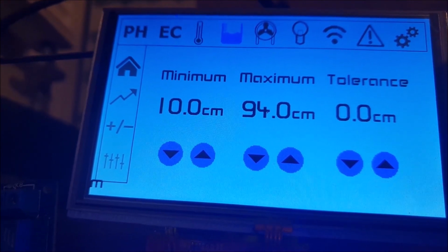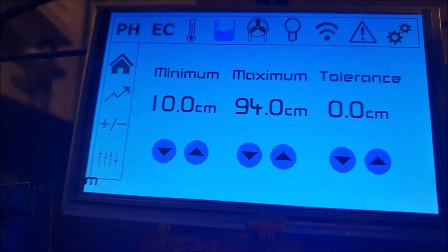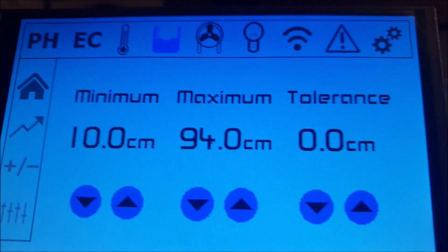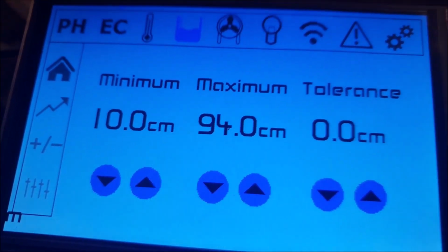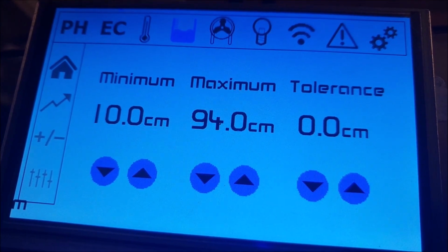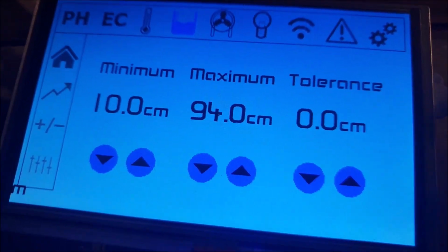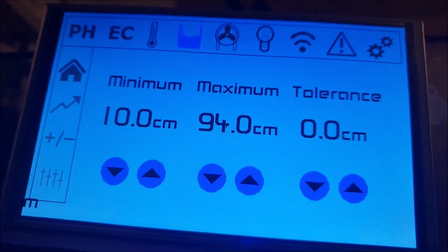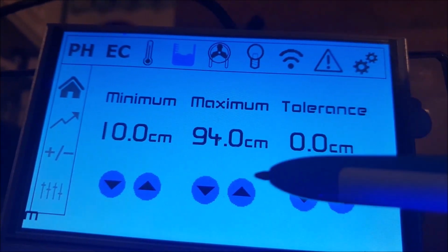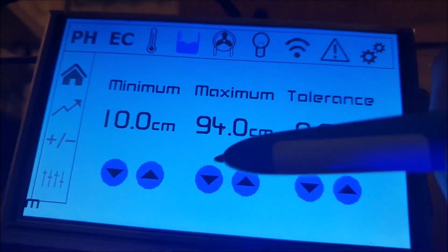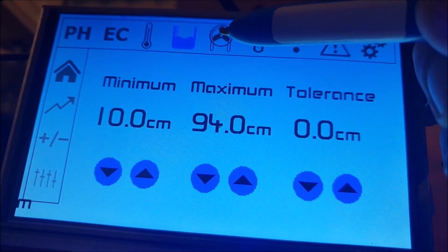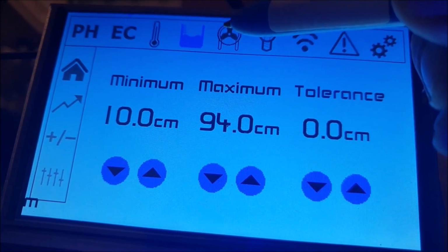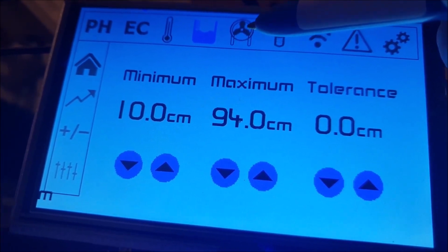not only am I not using a calibration chip for the X and Y, I'm not even using a touch chip, this display driver. I'd have to turn off the LED, we'll show you in a minute, but the display driver does have special outputs for you to use a touch chip that costs, I think, about £5, that's far more accurate. And I think that chip itself also calibrates the display as well. So you get far more accuracy on your touch and you don't get these ghost bounces. We're having to use interrupts here to actually monitor the touches, so it's not the best. Anyway, that's the water level page.